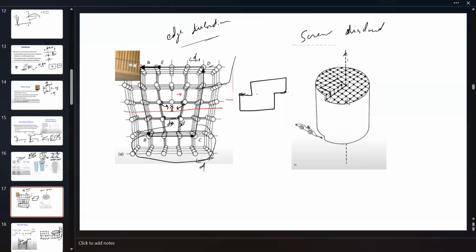You can have screw dislocations. This is the edge dislocation, and this is the screw dislocation. All these dislocation methods are how plastic deformation happens in your sample. So you apply this strain, slowly these dislocations migrate toward one edge, one side, and that causes the plastic deformation.